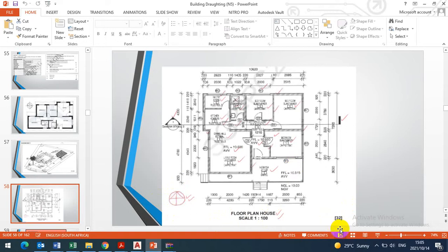And then you'll be able to get the 32 marks if your floor plan is fully detailed like that. I see the passage is 1 to 10. It's okay, but I said the minimum was 900. You see, this is 955 here. This is a bigger passage. Minimum passage is what? 900. 1.2 is also fine. It's big. It's okay. Doors have got window door codes. Windows with window codes. This is a fully detailed drawing. You will get the marks.